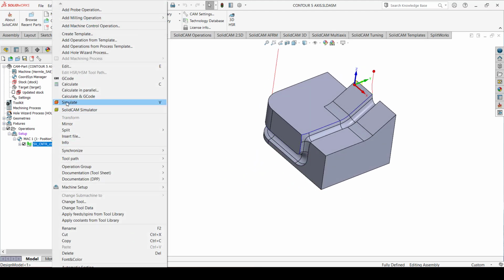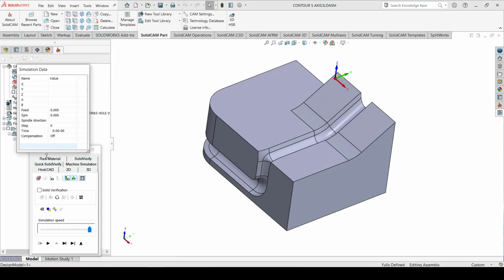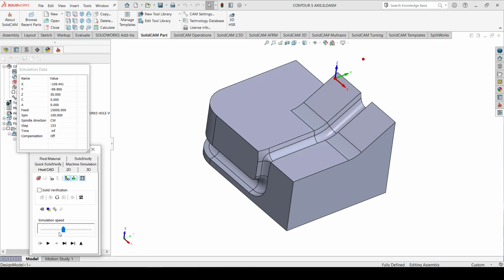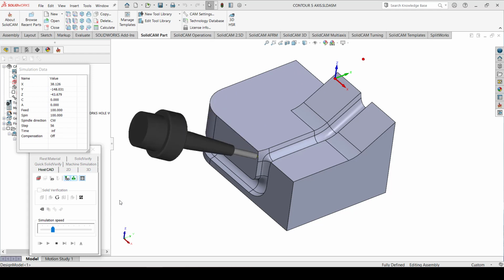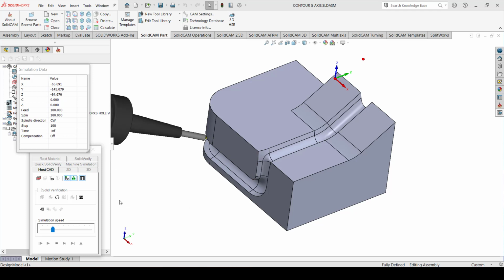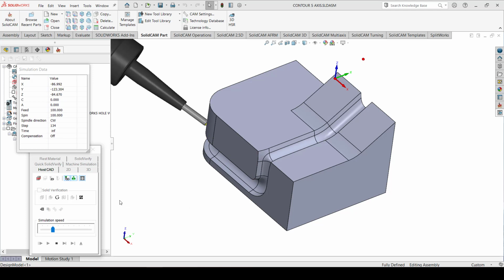And if you run the simulation, this is how it's going to look. So let's reduce the speed. It just follows the curve, nothing else. It follows the curve, and the orientation lines determine the tool axis direction. So you can see that you can do a very nice tool path here to do the chamfer of a particular part.